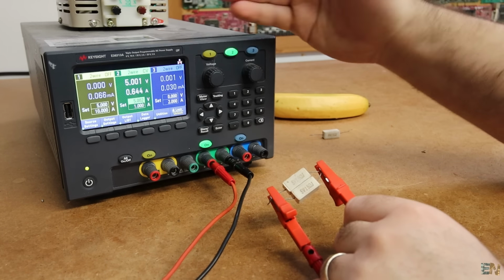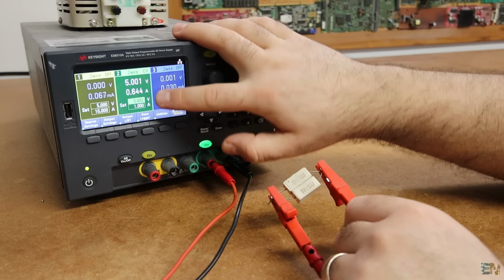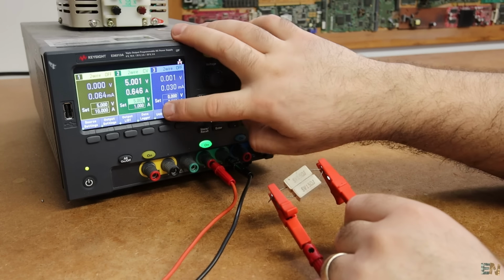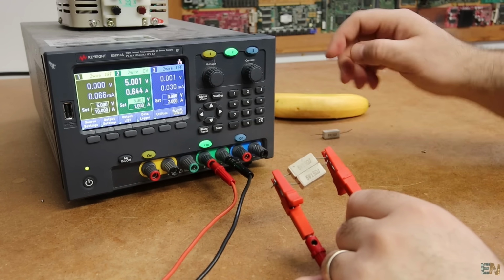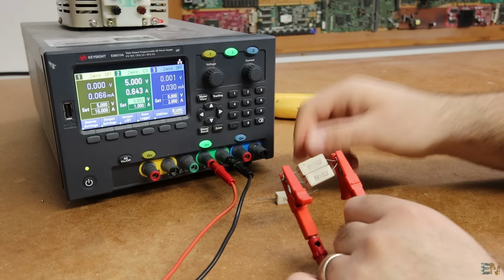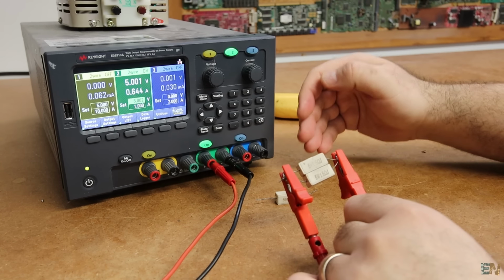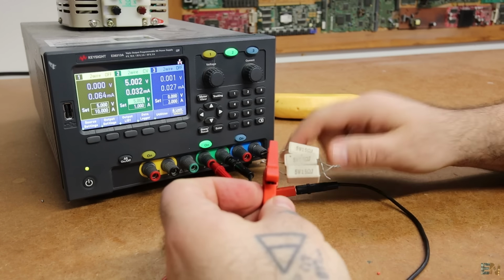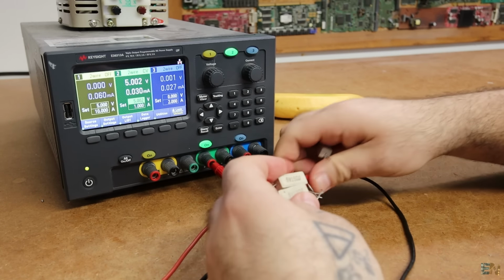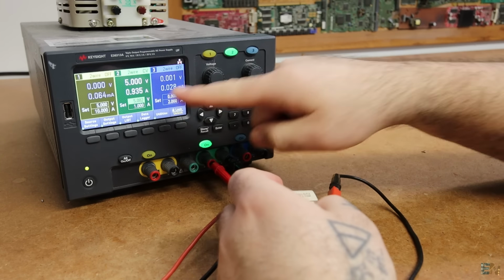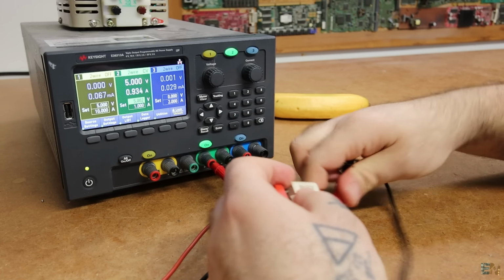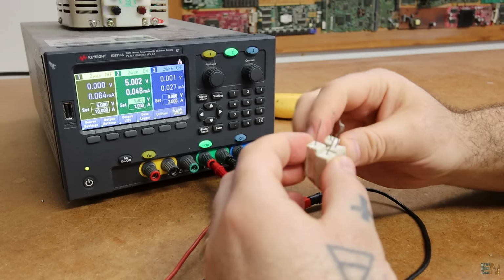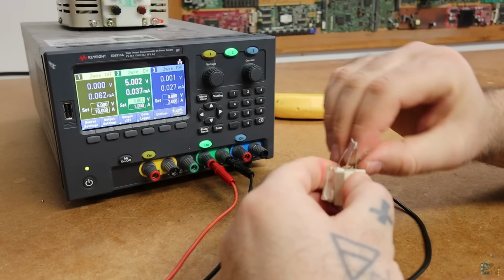So we can still increase the power output, which is the multiplication between the current and the voltage, but we can do that until we reach the maximum current value, which is 1 amp. So let's see what will happen if I surpass the maximum current value. With 3 resistors in parallel, the current value is still not surpassed because we have 300 times 3, which is 900 milliamps. What I will do is add 4 of these resistors in parallel, so we'll get more than 1 amp of current. Let's just see that.